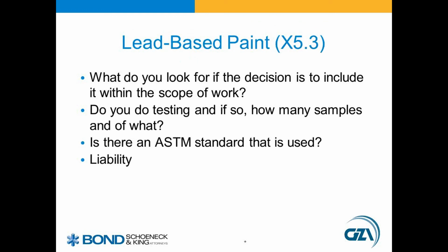Concerns over lead-based paint have been around for quite a while. Much like with asbestos, if your building was constructed before 1978, it's pretty smart to do a lead-based paint survey. The Consumer Product Safety Improvement Act of 2008 established a lead paint limit of 0.009%. That's 90 parts per million. If anything comes back higher than that, you know you've got lead-based paint.